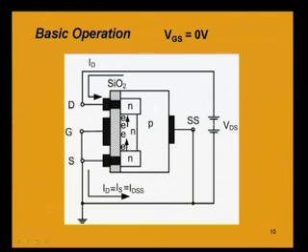So, there will be flow of electrons through the n channel between the two n type materials. So, the conventional current flow will be as shown in this arrow mark, and that current is, say, the drain current flowing, and it will be entering into the negative terminal of VDS. So, drain current and source current both are equal.